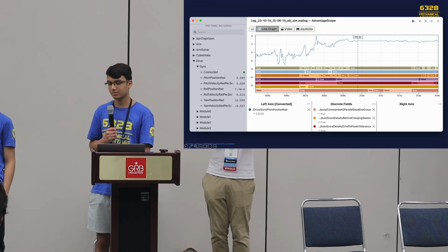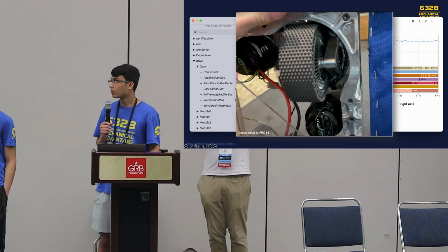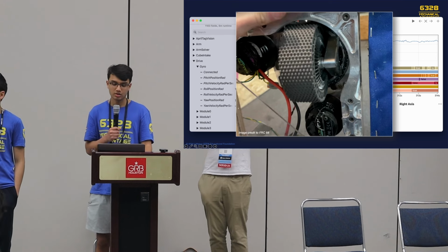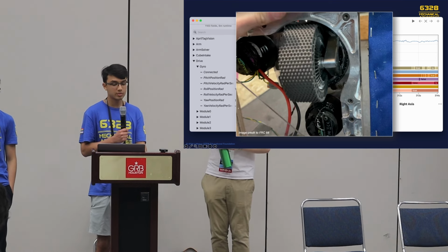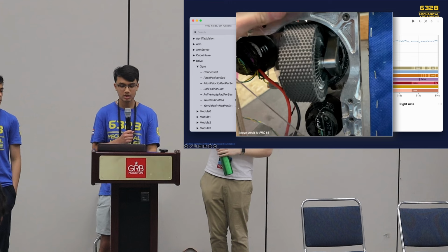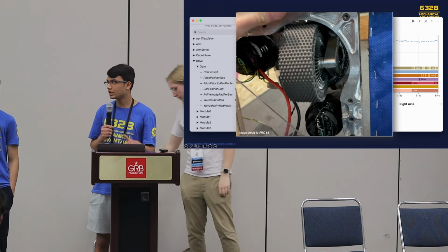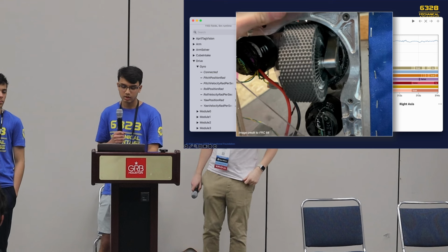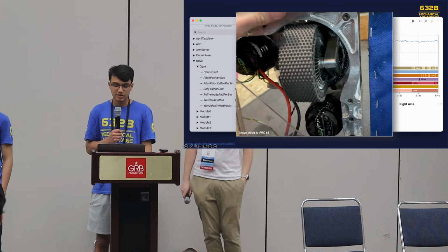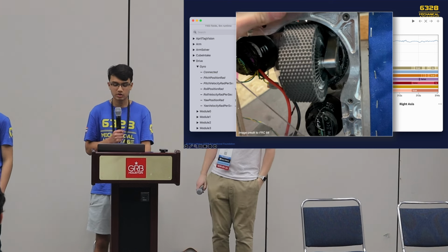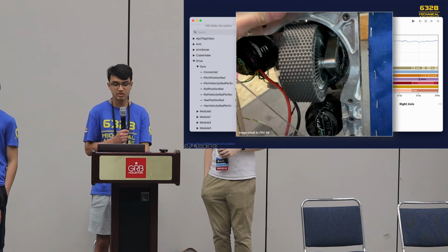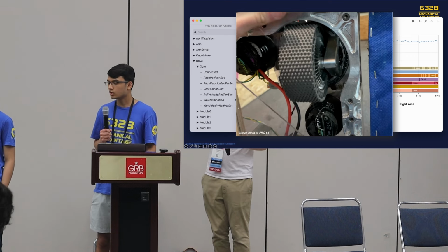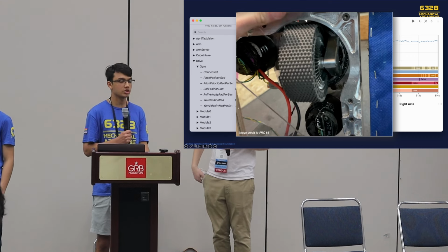So what was the cause? Well, actually, we were testing out our new TPU wheels at this event, which had a less stiff spring material between the hub and the tread. Because our robot had a slightly uneven weight distribution, one side of the robot was compressed more than the other, making us off-center. This could have been some mysterious fluke that was never solved. However, simulation replay gave us a definitive cause. We could have solved this by either switching wheels or adjusting our tolerance.